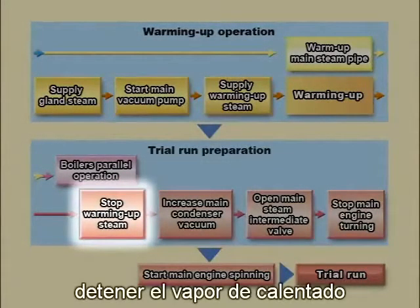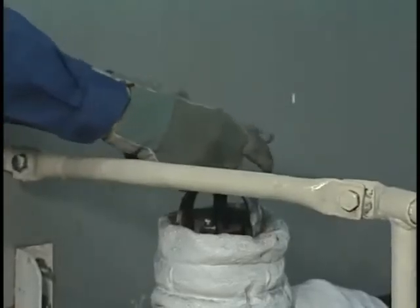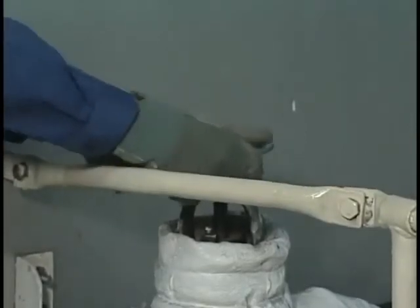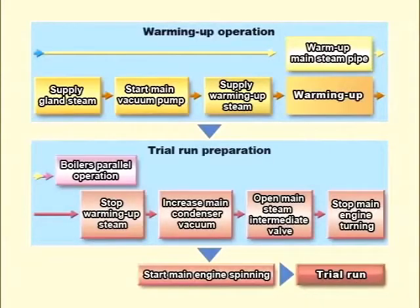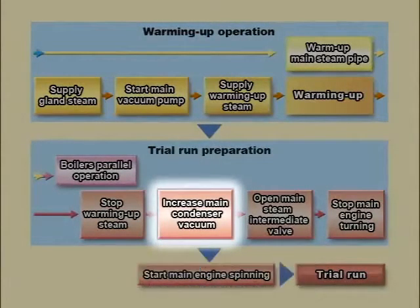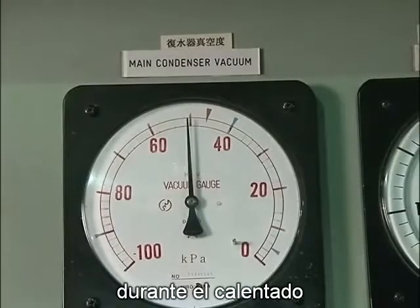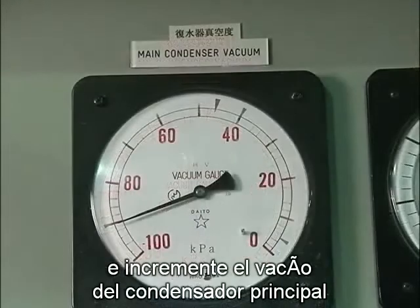Stop warming up steam. Stop the supply of warming up steam by closing the desuperheated steam stop valve and warming up valve. Increase main condenser vacuum. Although the vacuum of the main condenser was maintained at a low level during warming up, now start continuous running of the main vacuum pump and increase the vacuum of the main condenser.